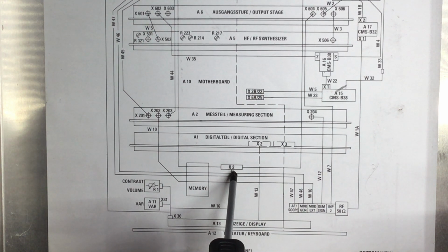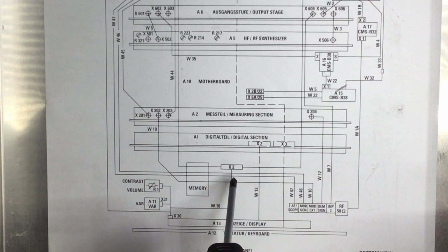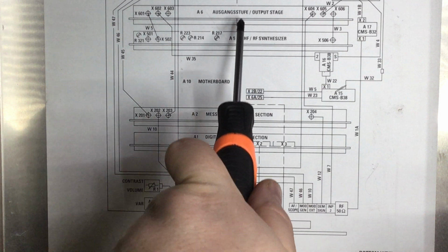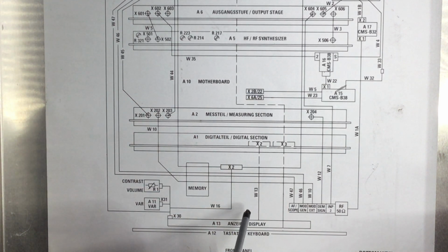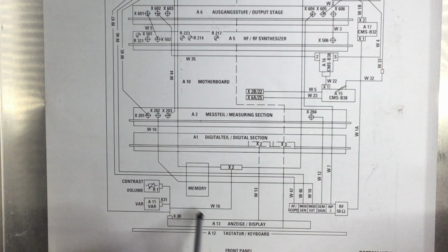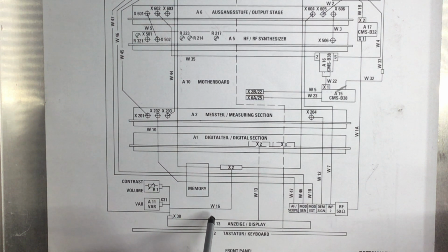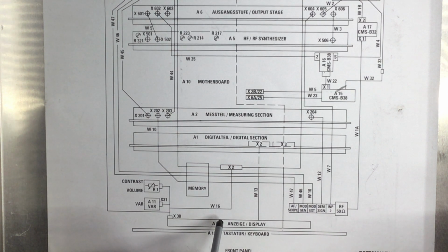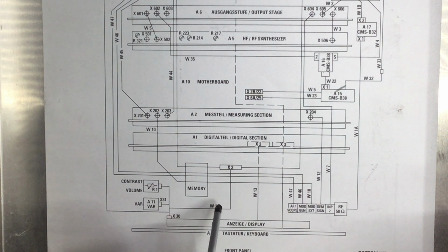Looks like it's got a motherboard connection, and there's a data bus then that's shared amongst all these modules on the motherboard. So it looks as if the variable control shares that connection along with the contrast control and the speaker and other things on that flex, and also it may be that there's a dry joint or intermittent connection or something like that possibly.